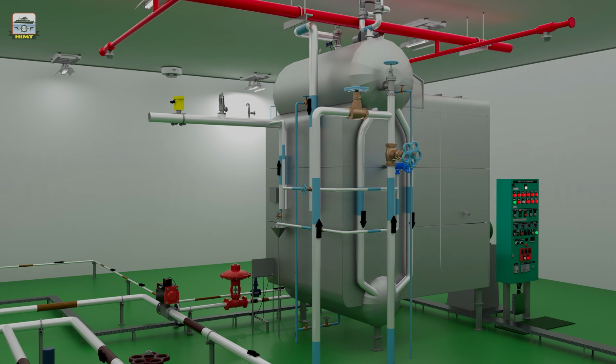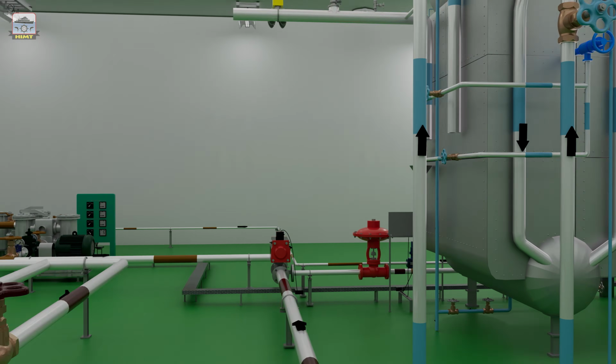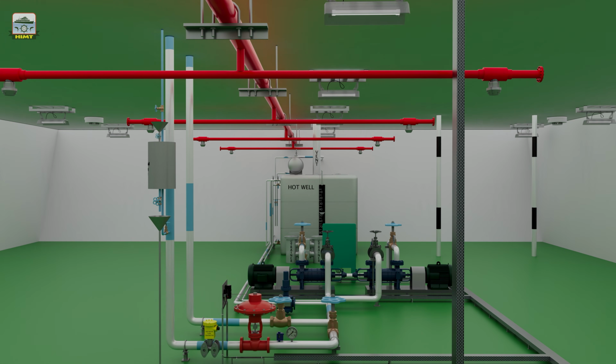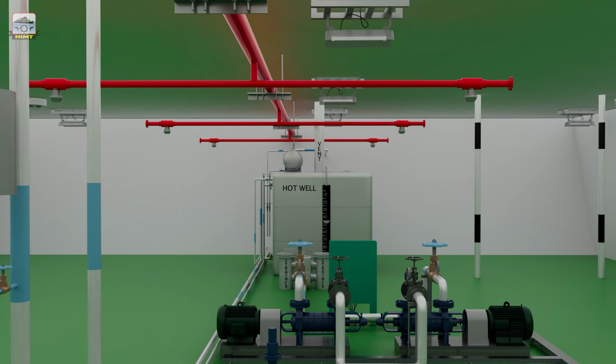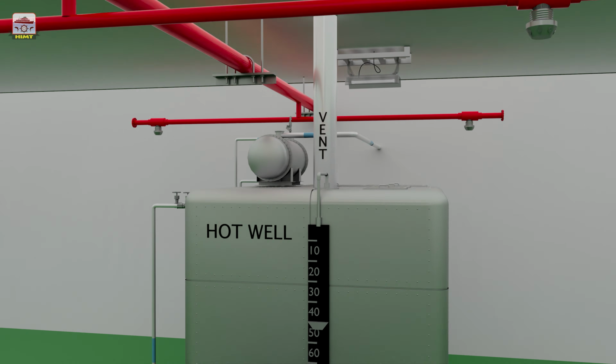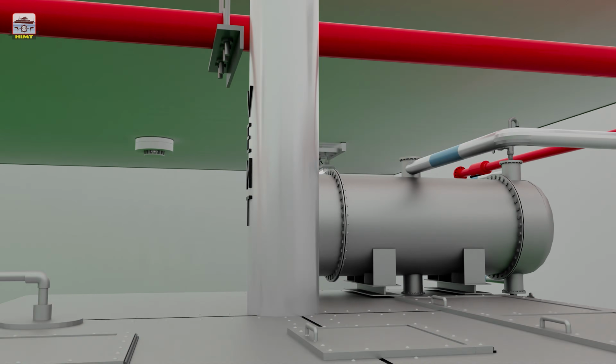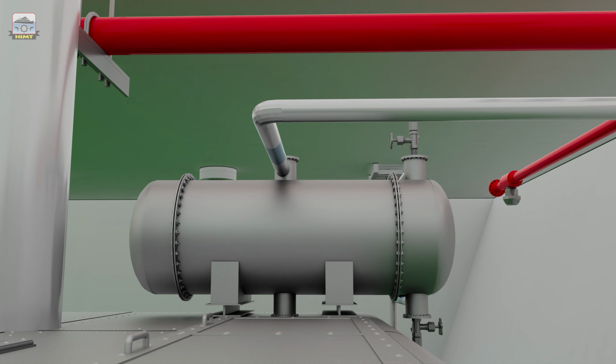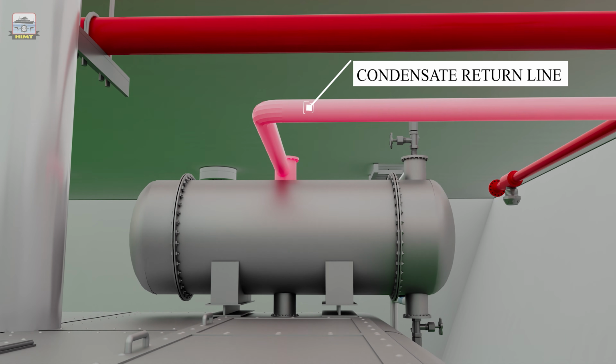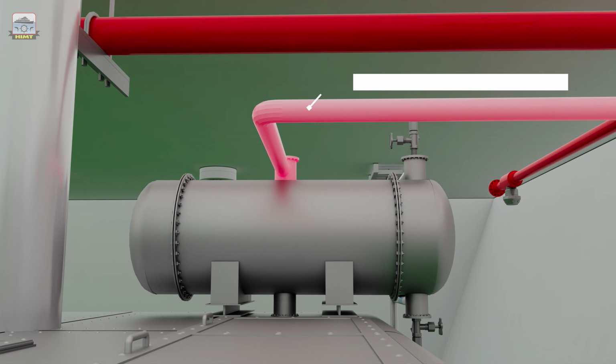The steam leaves various heating coils fitted in fuel systems, lube oil systems, bilge system, sludge system, etc. through the steam traps. Even though the steam traps allow only the condensate to come out of the heating coil, part of the condensate flashes back to steam due to low pressure present in the condensate return line. This steam has to be condensed so that the condensate can be pumped back to the boiler. The steam coming in this condensate return line is condensed by this condenser.